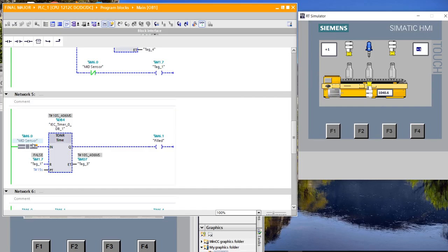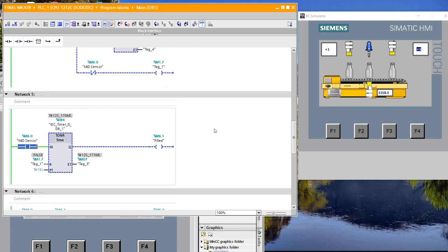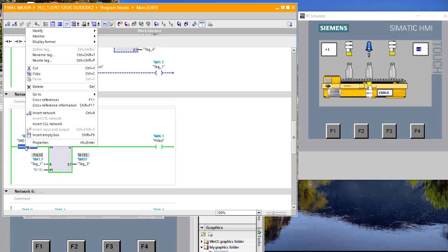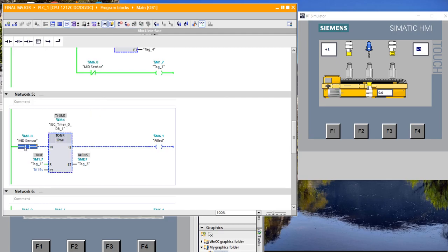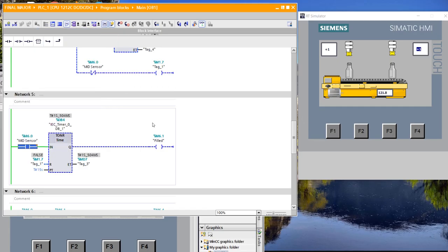So this way, if I have attached a new sensor now here, then the time starts from the time at which it had stopped. Overall the system is working properly. The only problem is that when the mid sensor fails, at that time it stops the solenoid valve and timer, but the motor does not get stopped.